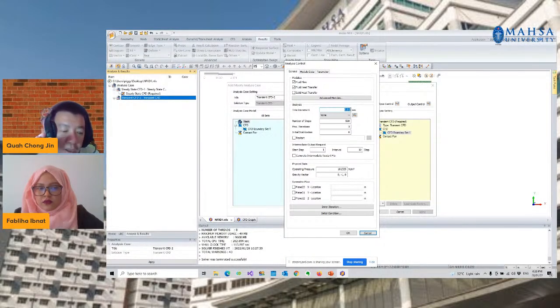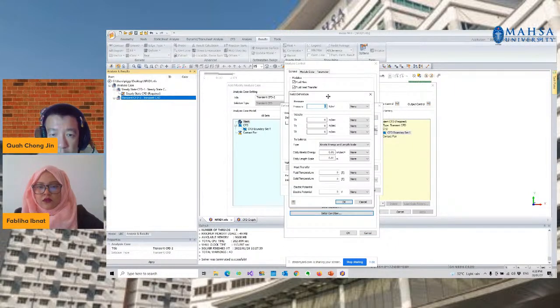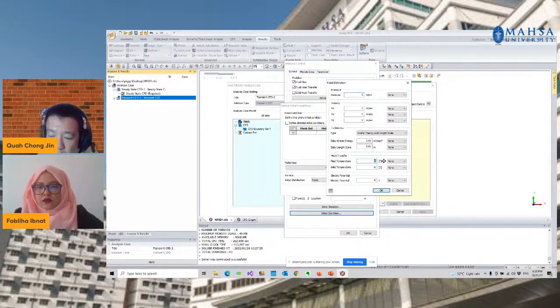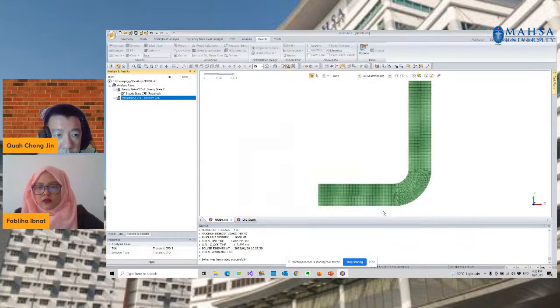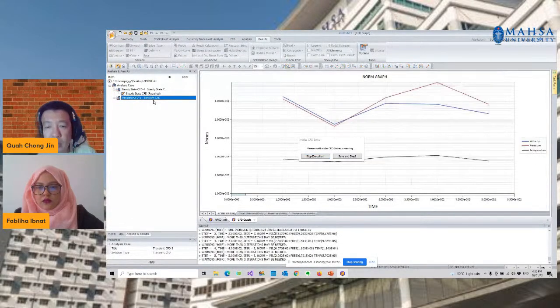Unless we want to go for accuracy, then we will have to compare with the experimental study. Then we should be able to change those values accordingly, in an appropriate manner, based on the training or based on the experience that you're going to have. And of course, don't forget to set up the fluid temperature of 8 degrees. Remember to save, and you'll be able to run.